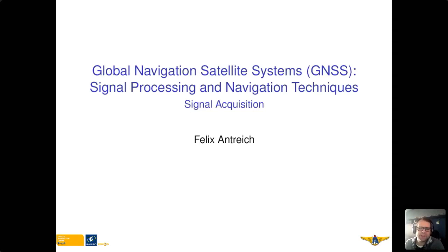I already commented that we need to initialize somehow this iterative process, which ended up in a formulation that is a basic delay lock loop for the time delay estimation. Today the topic is signal acquisition, and this is exactly this initialization process.